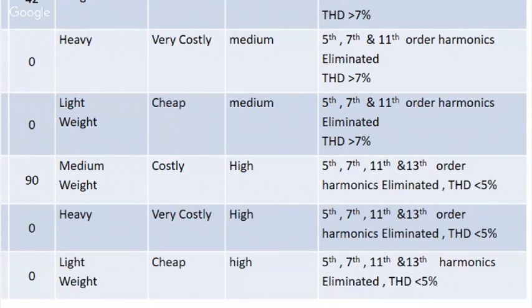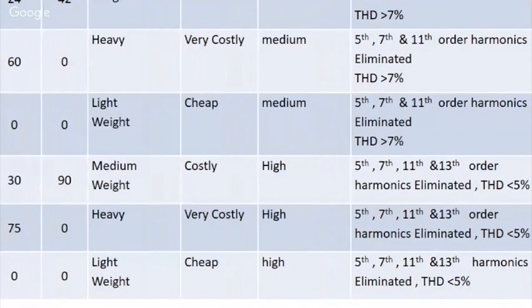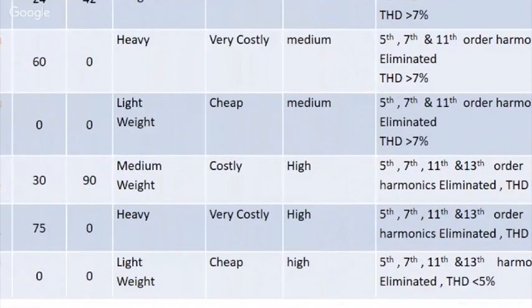It is the IEEE 519 standard. I think it has a year also, because it was revised again in 2006, but this one is 1996. You can check it on the internet. According to my knowledge, it is 1996. So the IEEE 519 standard 1996 says the total THD should be less than 5%, and the individual harmonic should be less than 3%.